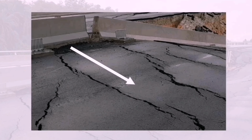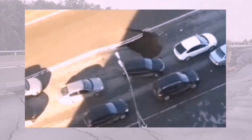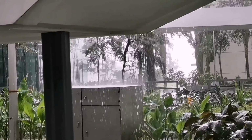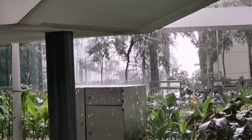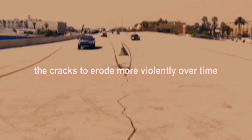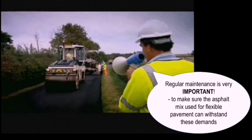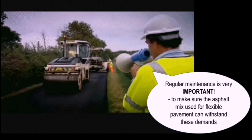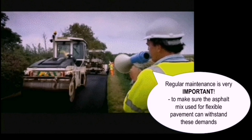Transverse cracks start from the surface of the pavement. If transverse cracks are not repaired immediately, they will gradually sink below the surface. Weather change and climate change will make the damage more critical, such as heavy rain. They will cause the cracks to erode more violently over time. Due to this kind of problem, regular maintenance is very important to make sure the asphalt used for flexible pavement can withstand this demand.